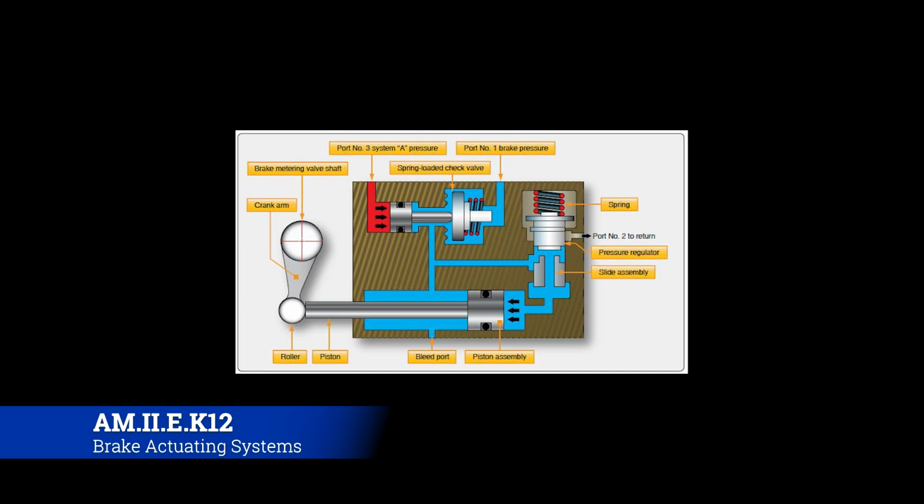They're all going to look very, very different. Airbus uses three independent hydraulic systems plus the RAT, and they're all intermingled and mixed, which in my opinion is probably actually superior. Their hydraulic system, while more complicated and able to lead to more problems, is probably more redundant. But essentially, they all follow this same sort of sequence of events, with slight deviations.